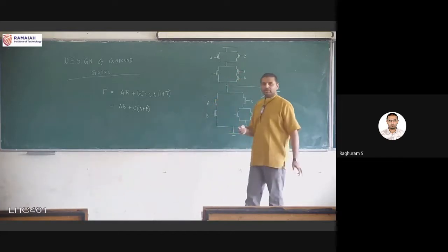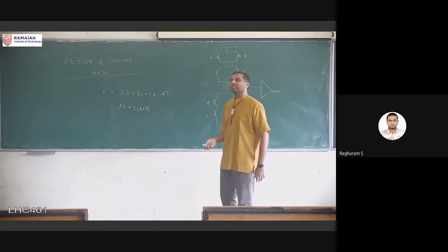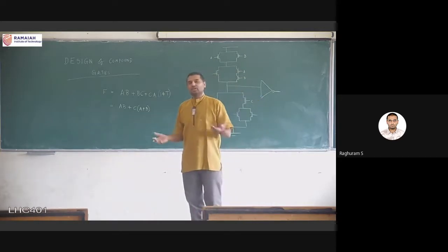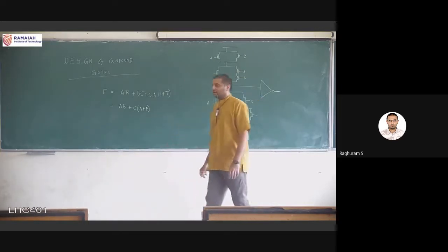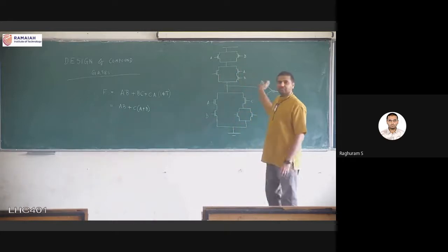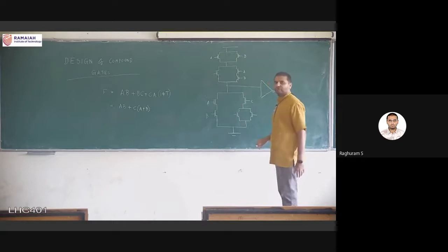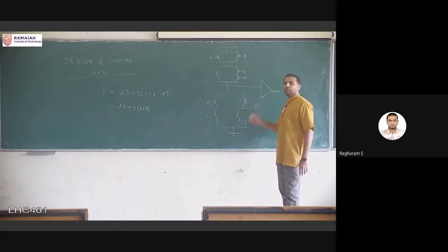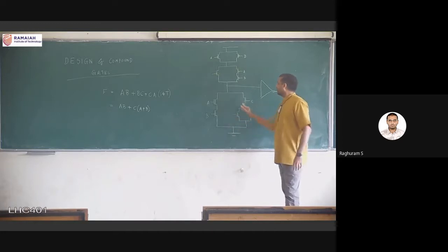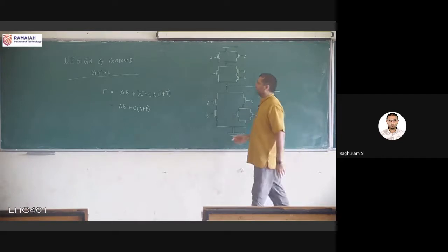Again, I'm being a little lazy. I shouldn't mix logic and circuit symbols, because this is a circuit. This is a gate level or logic symbol, but since we all know very well the static CMOS inverter, I don't want to draw the whole thing. But how many transistors here? 1, 2, 3, 4, 5. So 5 twos are 10 plus 2, 12 transistors.